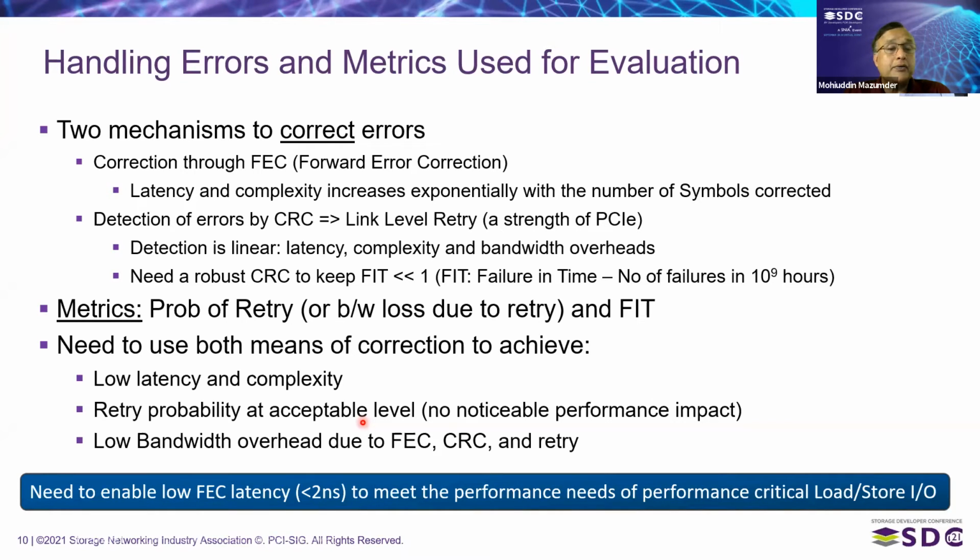So what we try to do is take advantage of the PCIe link level retry mechanism and strong detection through CRC, and then combine those two to implement a low latency light FEC.